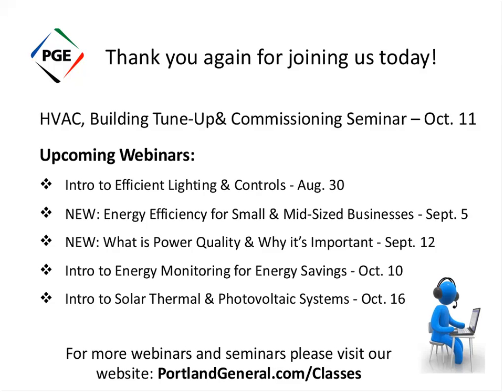So moving on from that, we deal with a lot of facilities that do have multiple meters, and so then do your benchmarking and figure out which meter has the most use, for example. Maybe you want to concentrate your effort on the largest energy consumer. If you're an operator of a large office building, for example, you may have a house meter that is providing energy to the core lighting and maybe the lobby space, but that energy consumption is going to be nothing compared to the occupied areas of the office. So start off with, what meters can I affect, and then move on to what are the biggest energy consumers that I'm dealing with.